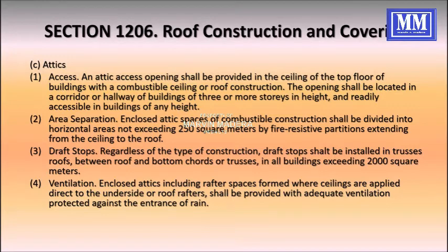In the case of ventilation for attics, enclosed attics including rafter spaces formed where ceilings are applied directly to the underside of roof rafters shall be provided with adequate ventilation protected against the entrance of rain.